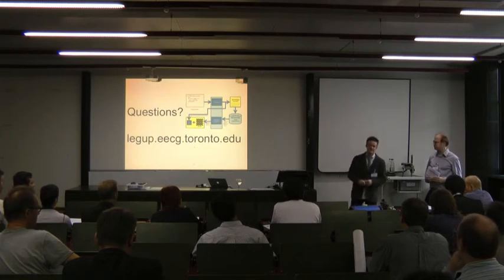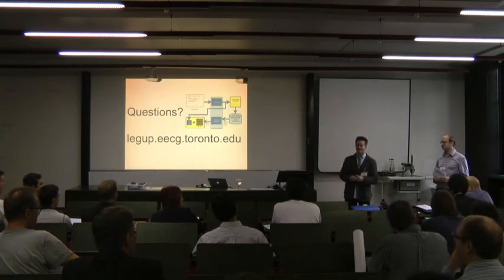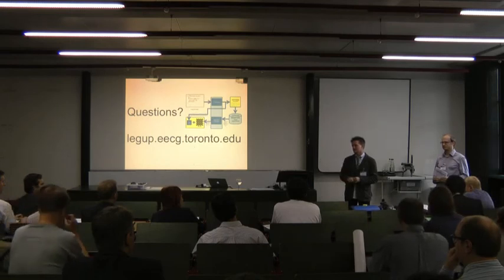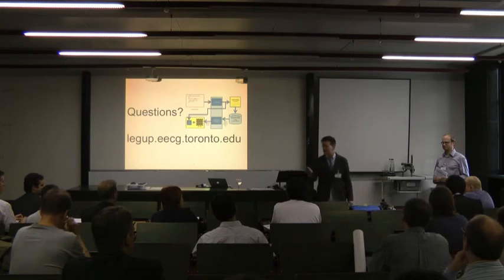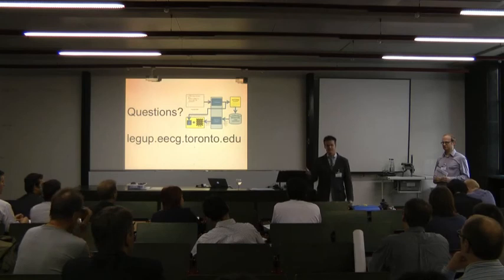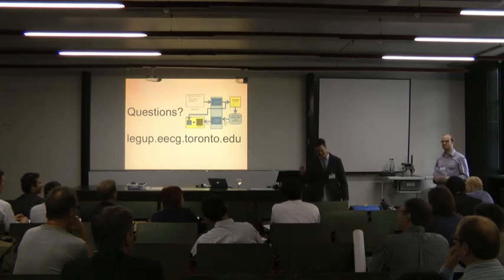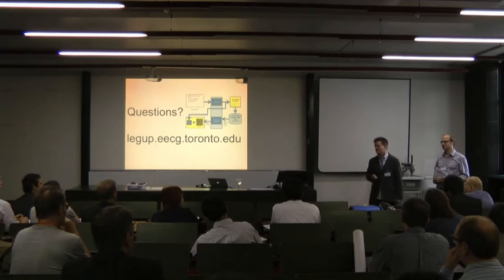We haven't done anything on dynamic reconfiguration. We probably need to hook up with some third-party tools to swap in and swap out accelerators. We haven't done anything like that, and our support for that is not that strong. So say I choose this function, this function, this function, and this function to run as accelerators, and I can't fit them on the FPGA. You yourself would have to go back and get rid of some of those lines in the Tcl file. You would have to manually move some back onto the processor.